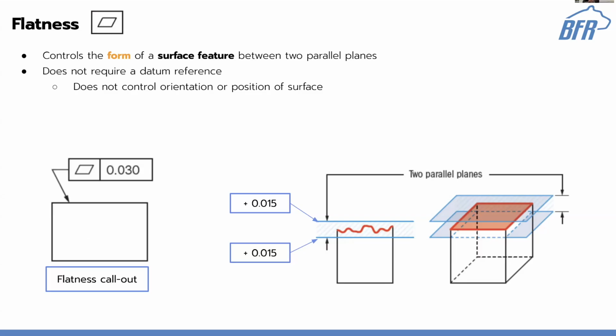But you can remeasure certain things if you have an idea of what might be going on. We were pretty sure that there was just some random point that was sticking out, or it was too deep or something, some random chip that might have been affecting it. In that case, the majority of the surface is flat, and therefore you can use it. So we went back, checked it. It was actually still flat. So it's important to understand what it actually means when it says something's out of tolerance for flatness, right?